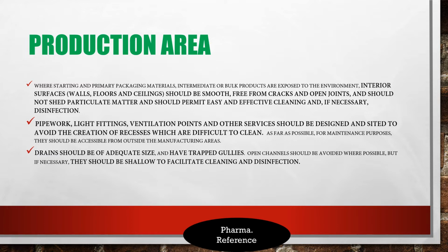The drains should be of adequate size and have trapped gullies. Open channels should be avoided where possible, but if necessary, they should be shallow to facilitate cleaning and disinfection.